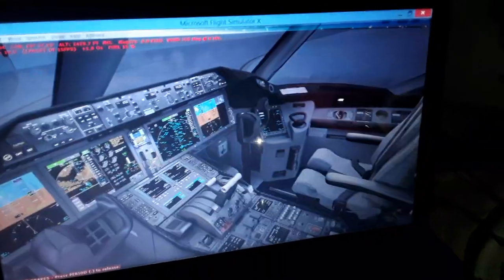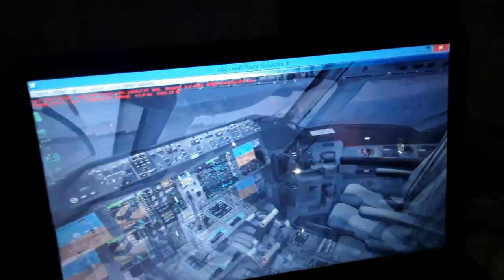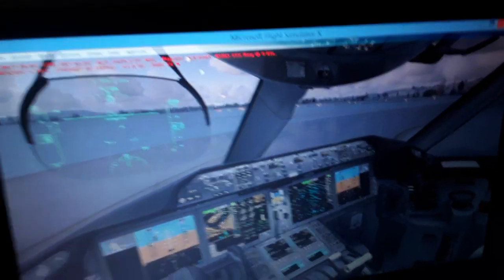So we're gonna have the magnetic heading of 136 degrees for runway 14 in the Zurich International Airport in Switzerland for approach and landing, and we're gonna use the LSZH localizer, the instrument landing system, for horizontal localizer alignment and vertical glide slope. We can tune the LSZH localizer here from the radio management panel. We can use the flight management computer automatically when we select the landing runway. So we're gonna have a complete flight plan from takeoff, climb, cruise, descent, approach and landing.